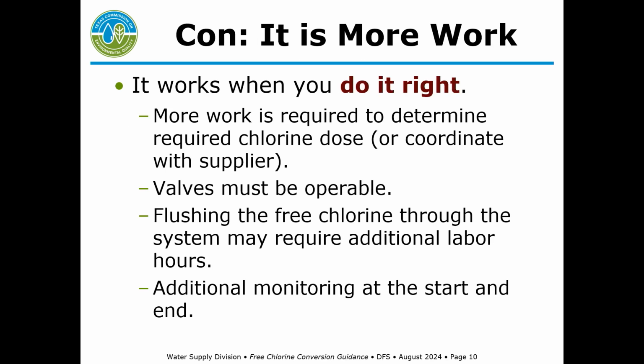So one of the cons is that you, as the manager and operators, do have to do a lot more work than normal during a free chlorine conversion. You've got to do some work ahead of time to figure out: are our chlorine injectors even big enough to breakpoint chlorinate? That could be an issue. How much chlorine are we going to have to add?